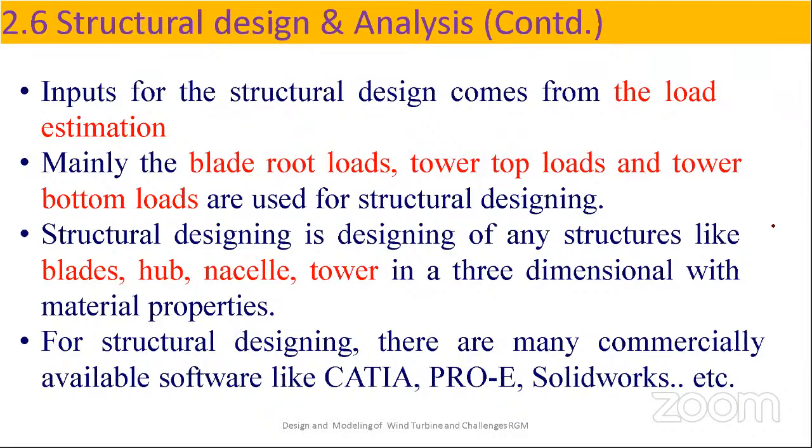Then the load estimation. And where is the load coming from? Mainly from the blade root and the tower top. I have explained to you the blade root and the tower top, all the components, and the tower bottom loads. So all these loads. And structural designing is designing of any structure like blades, hub, nacelle, tower.